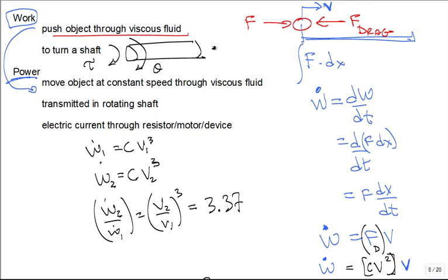So what is the work to turn a shaft of constant torque no matter how far I'm turning? It's the same torque. It's uniform torque, just like same force no matter how far I pushed it. Through an angle theta. What is the equation for the rotational work? Would it be integral tau d theta, which if they're constant, it's just tau delta theta, right? Just like if F is constant, it's F dx. True or false? How many people have already passed dynamics? Did you not do something like this for rotational dynamics? Yes, say yes, please. Yes, thank you very much.